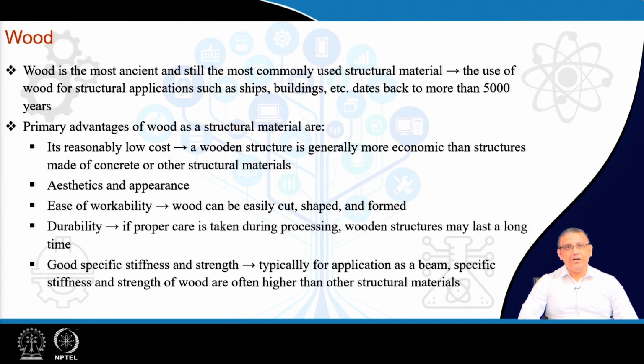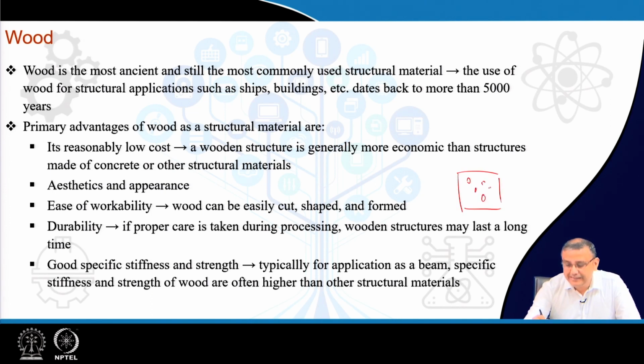That means, as we learned already, there are materials which are isotropic. In those materials, the properties are identical along all directions, and also there are materials which are not isotropic, or anisotropic. In these materials, the properties typically vary along different directions. Typical examples, as we have learned already in this course, are fiber reinforced composites. So, you know that if we have a material like this, where the reinforcement is in the form of particles like this, then the properties along all directions are identical.